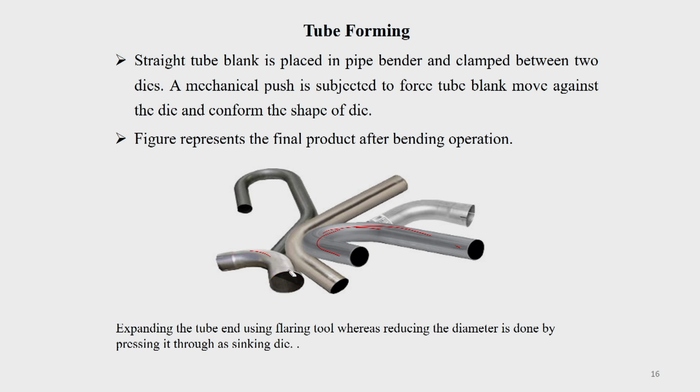Now, in case you want to expand the tube end, say like here, from the tube you want to expand this, then use a flaring tool. You insert the flaring tool and rotate it, and then finally you press it into that and you get that shape. So, that is a flaring tool.